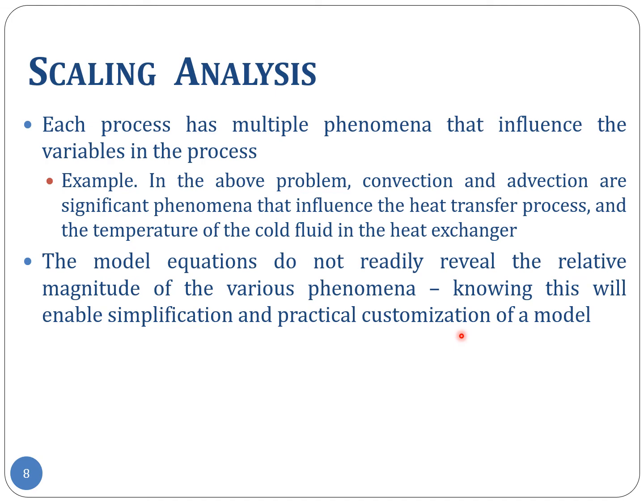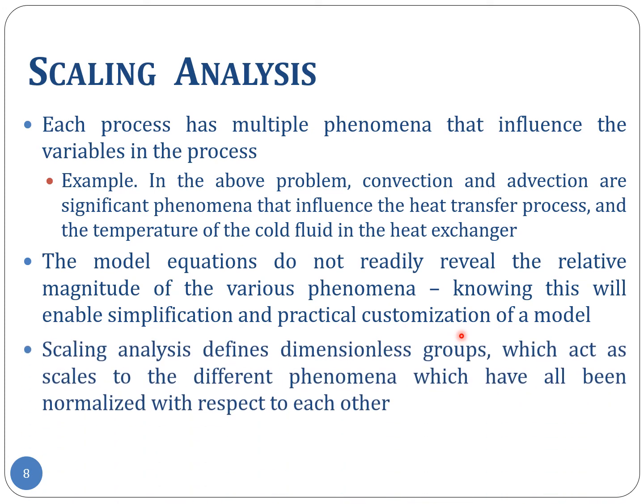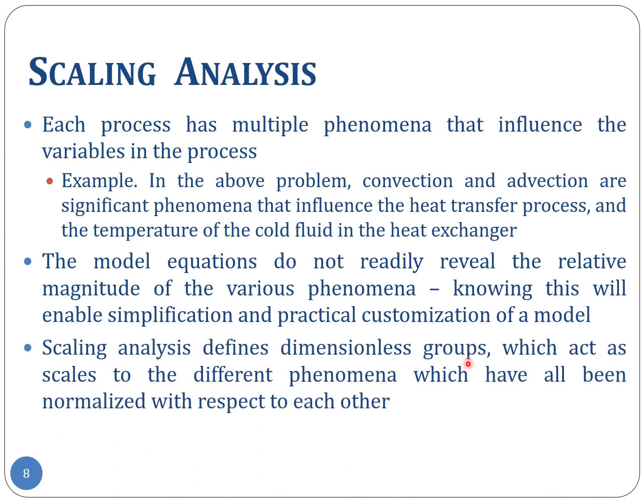But if we go through this analysis of rendering the model equation dimensionless, the scaling analysis defines dimensionless groups which act as scales to the different phenomena, which have all then been normalized with respect to each other. So the lambda term that we saw in that equation is the single dimensionless group that is going to determine how things are going to change. The left hand side, we had partial derivative with respect to a dimensionless time, and then partial derivative with respect to dimensionless position. All these are dimensionless, so everything varies between 0 to 1, or 0 to a few